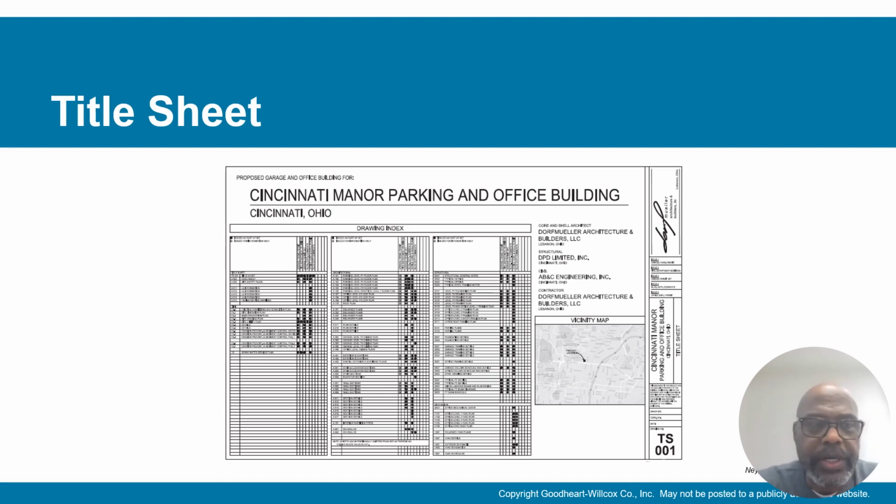I would say every print, but many times, we have a title sheet. The title sheet will be the main page that gives you a lot of information about the project. Part of that title sheet would be what they call a title block. On the right side of this print, you can see that rectangular shape would be all the information about the engineers, the architects, the construction company, and other important information.